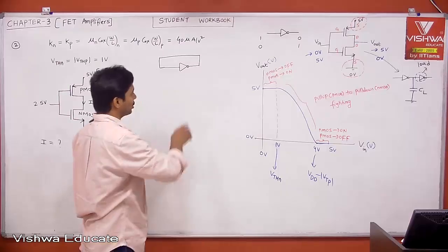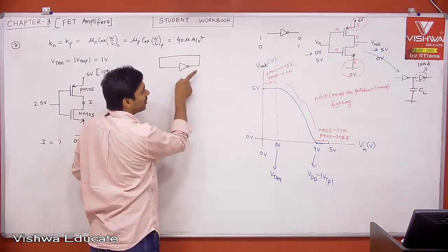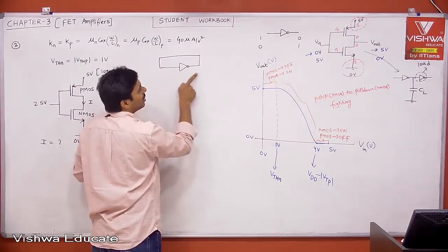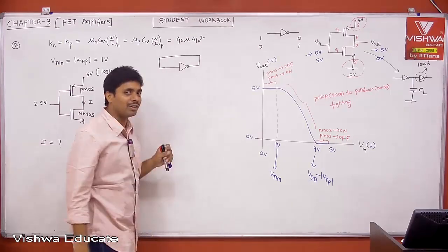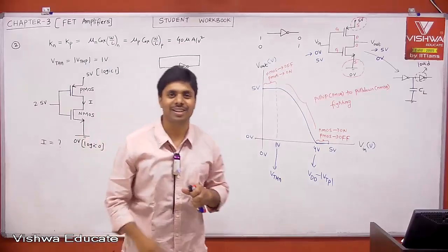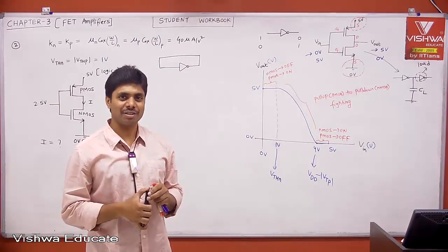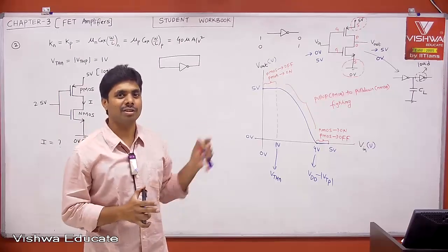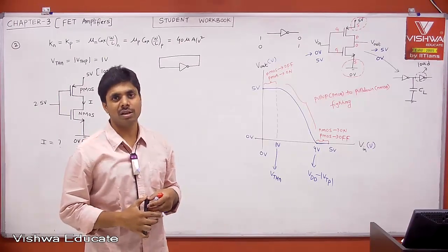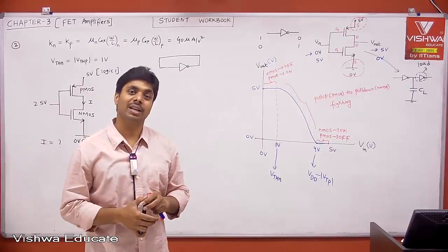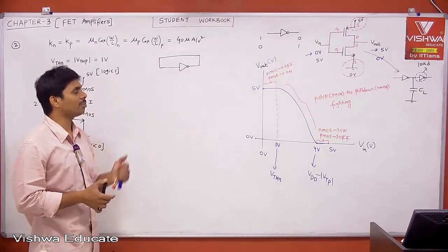Tell me, if I say this is 0, immediately this is 0. If you say this is 1, immediately this is 1. There is no delay element. That will not happen. That is not the solution. You may say 1 0 1 0 1 0, but it is not a ring oscillator. At least we should have an odd number of inverters, greater than 1, to get ring oscillation. This is not going to give a ring oscillation. But what is your output?